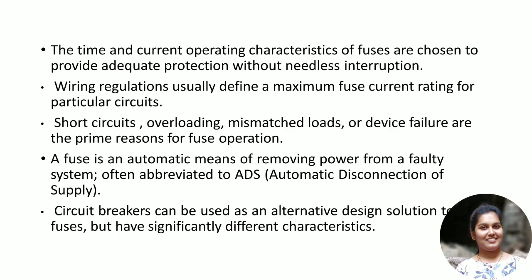So these are the major causes for fuse operation. A fuse is an automatic means of removing power from a faulty system, often abbreviated to ADS, automatic disconnection of supply. Circuit breakers can be used as an alternative design solution to fuses but have significantly different characteristics. These points have also been discussed in the previous session, that circuit breakers will do the same